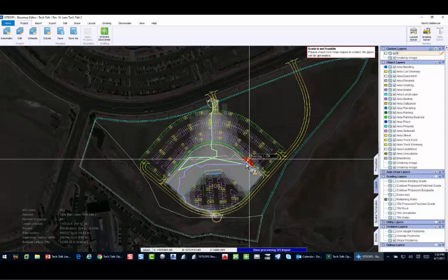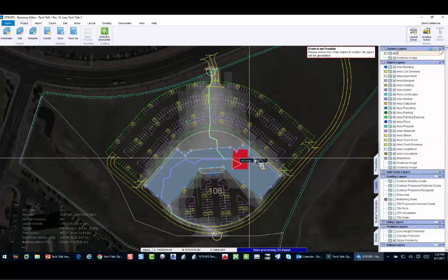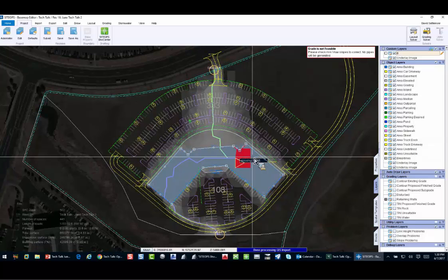Well, SITEOPS is telling me, based on what everybody wants on this project, no matter what, you can't build it. We're missing by 1.5 feet. Now, what if the client in this one says, I don't want any walls? So we got to now go to the client. Sorry, how do we solve a problem of grading? We physically can't build what he's asking for.